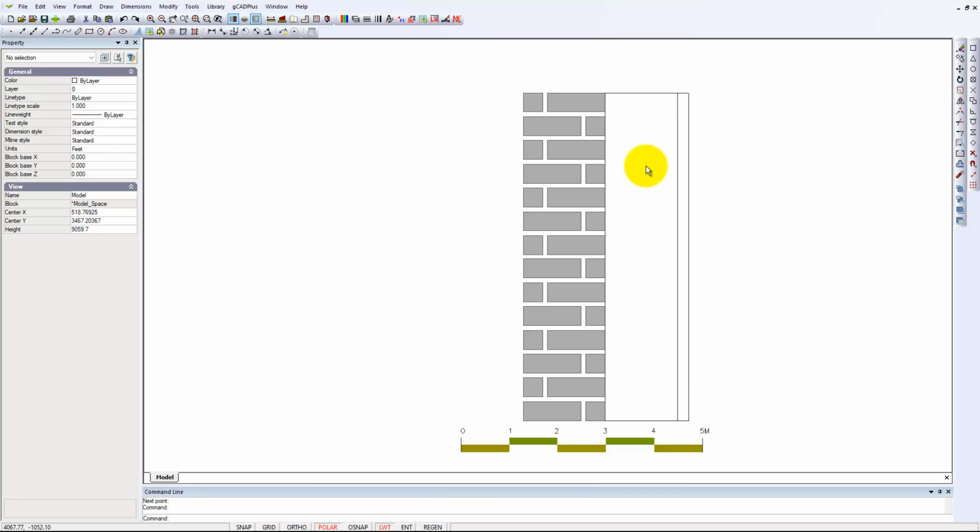Well, our test model has a 1500 millimeter wide garden bed, so I've just offset that line, and we've got a 230 millimeter double brick wall running here, and there are 2 ways to get this information into SketchUp. One is to export a raster image, a high resolution image file, and if we're going to do that, we need to include a scale bar, because as we bring the image into SketchUp, we will need to scale it so that we build a model on that image.